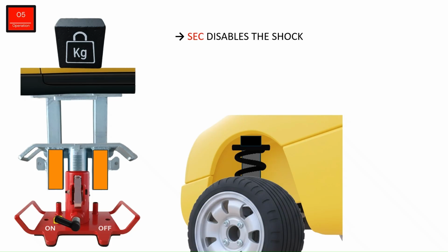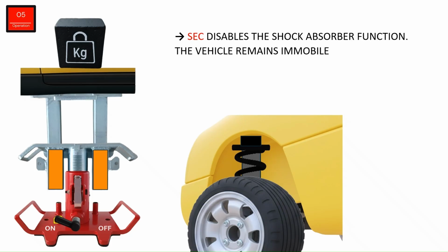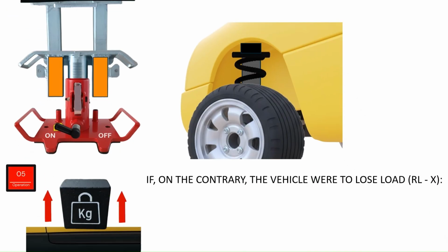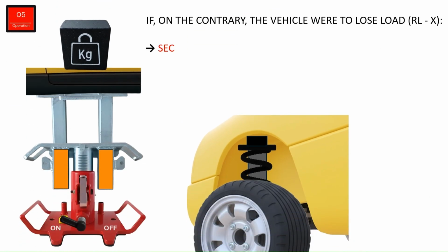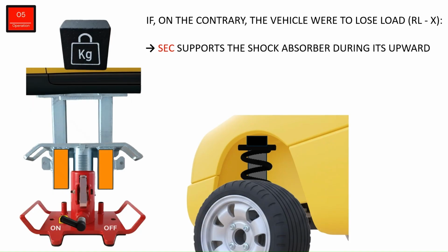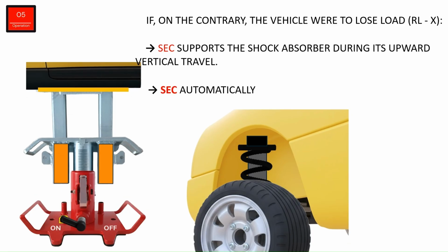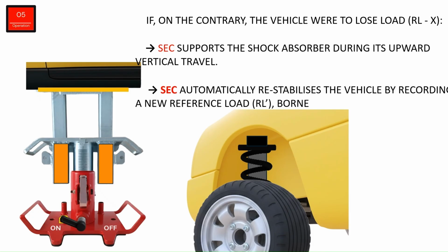SEC neutralizes the shock absorber function. The vehicle does not move. If the vehicle, on the contrary, loses load, SEC accompanies the shock absorber in its upward vertical movement. At that moment, SEC automatically re-stabilizes the vehicle, establishing a new reference load supported by the shock absorbers.